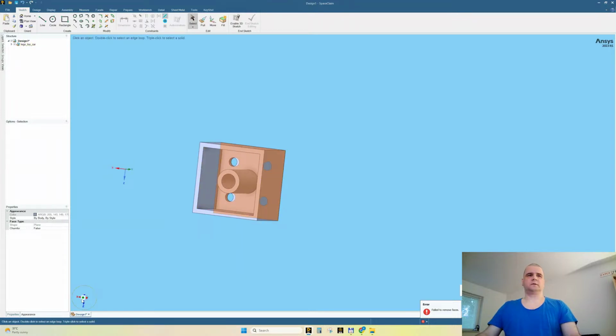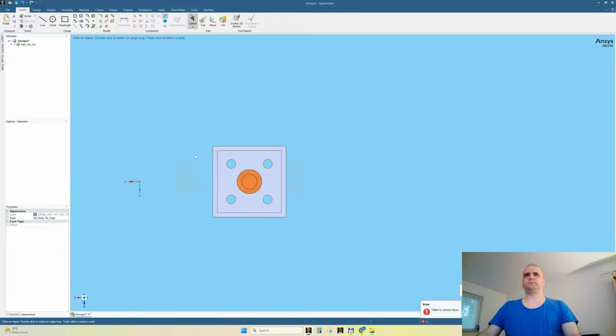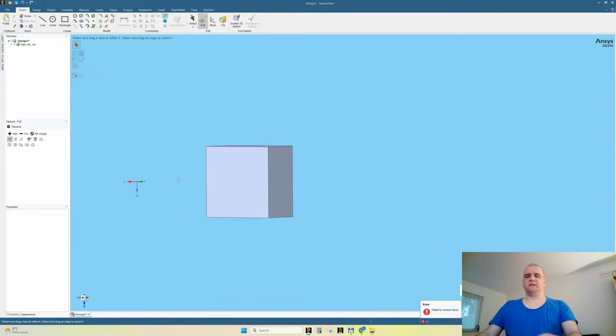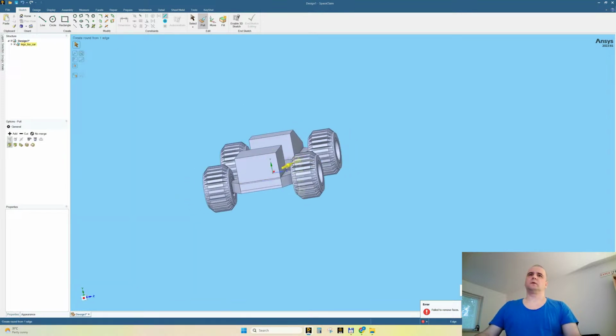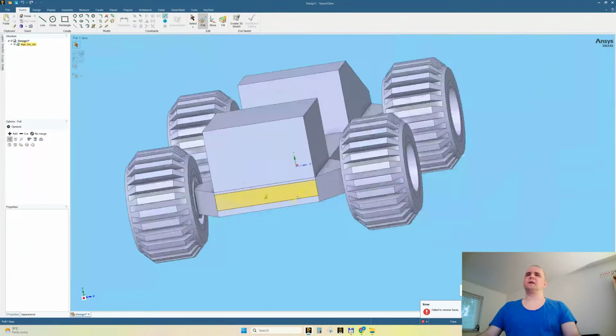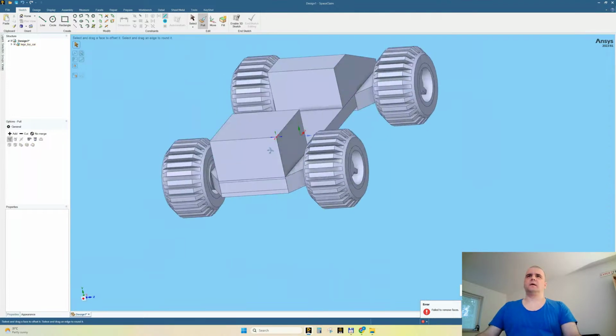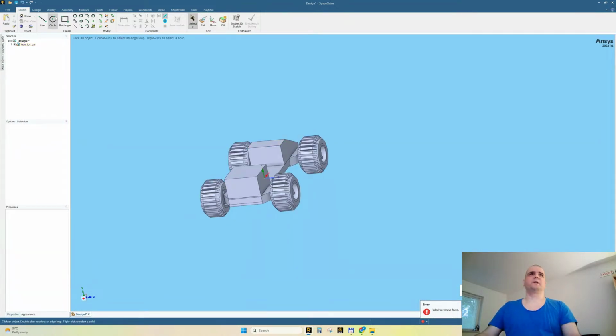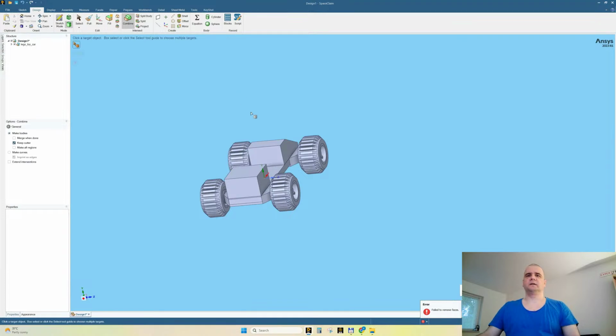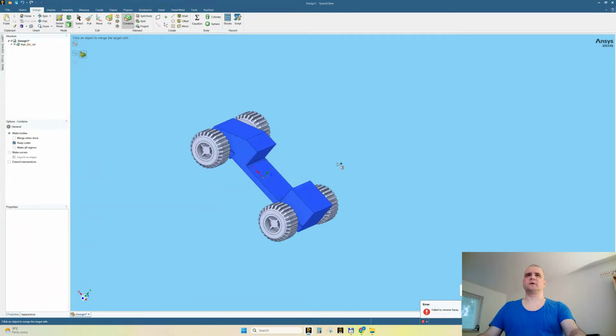Come on. Pull up to this face, show all. Now my intention is to make some Boolean operations, design, combine, with Control pressed here, here, here, here. Does it work or not? Let's see.